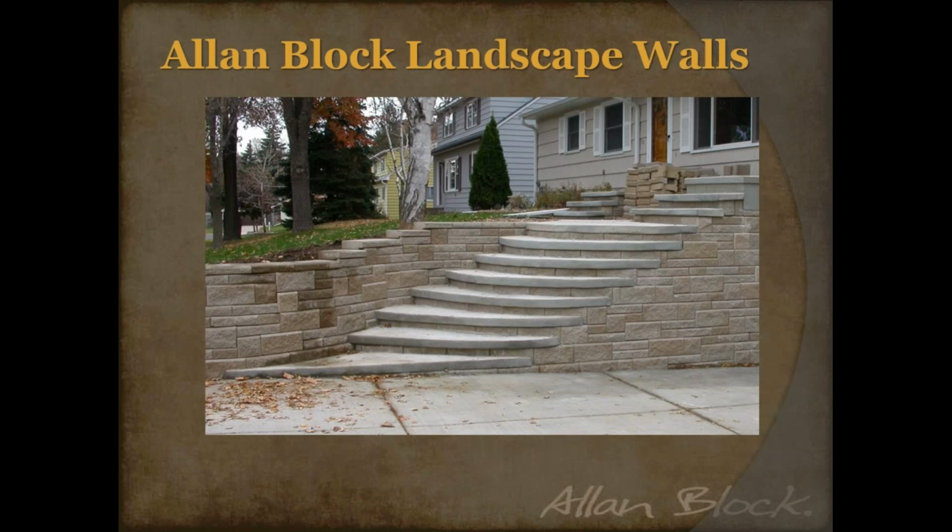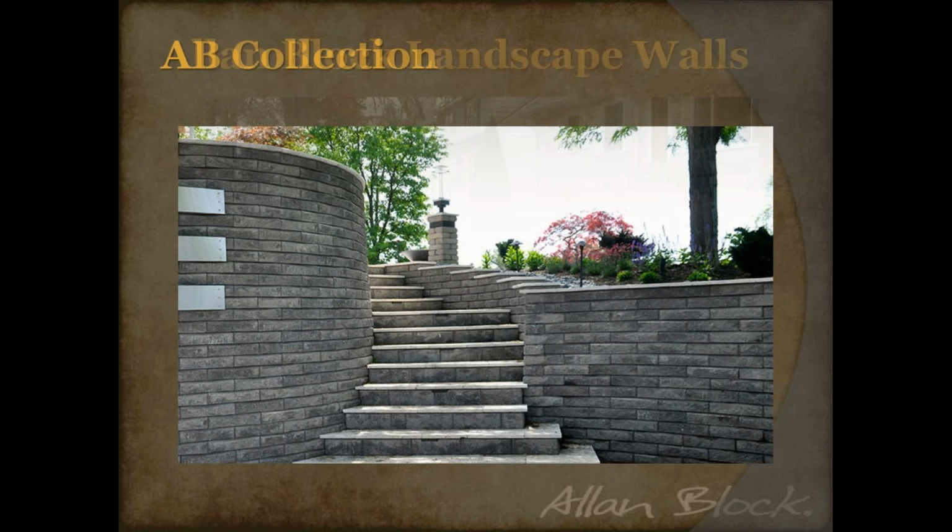Don't be too critical if you look at it, but I just did that inside and outside corner over here, if you remember, and then I just feathered each course off and fanned it out to create the stairs. And then I just did some 90-degree returns and started building my secondary wall to retain that soil. Obviously, it's not done yet. I still had to put the railings and stuff on there when this picture was taken, but a great way to build a set of steps when it was all said and done.